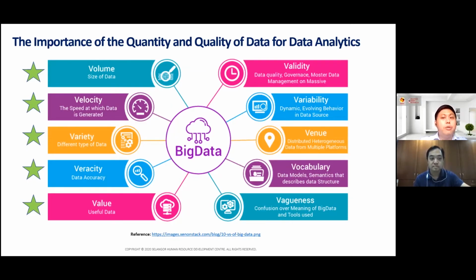And velocity. Now, if your machine is operating at 5 seconds, right? Every operation is 5 seconds. And if you collect your data every 10 seconds, you're actually sampling your data at the wrong sample rate, right? So velocity actually tells you what your sample rate is. And therefore, if it's running at 5 seconds per part, you actually need to sample at a shorter sampling time, maybe every second, right? To get the valuable data for you.